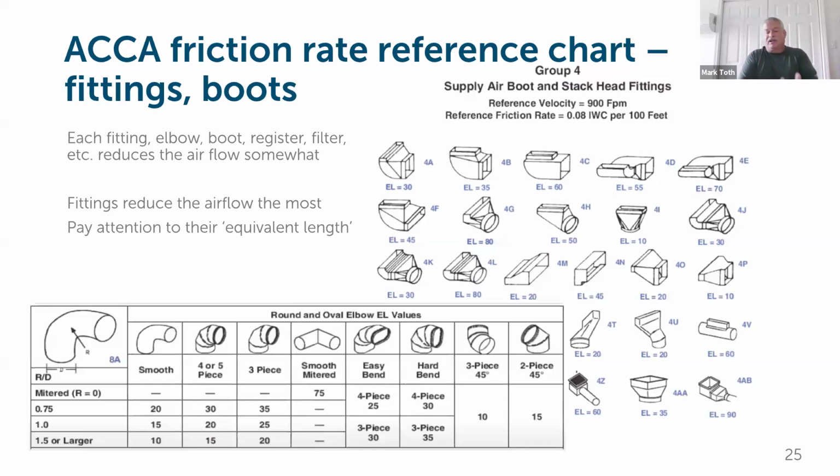So that's another reason, as we talked about last week, to oversize your unit. Always get a bigger unit than you think you need because of multiple reasons. Last week we talked about efficiency, we talked about being quiet. But another thing is that if you design this duct system or someone does it for you, you've chosen a 100 CFM unit because you need 100 CFM. You may get done and your final measurement is 50, 60, 80 CFM. If you have a larger unit that's adjustable, you can always turn up your fan speeds to overcome the duct system that you've created.